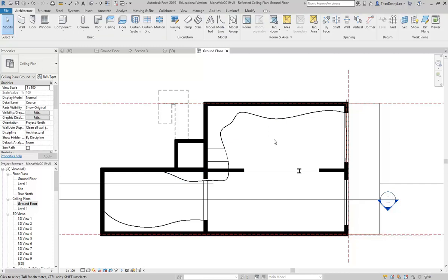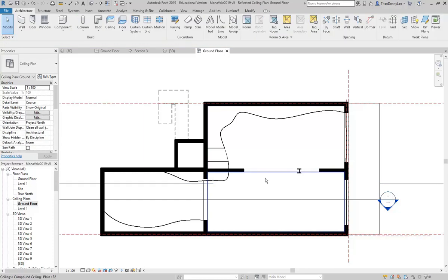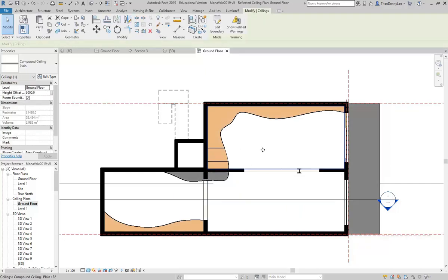That's the way Revit is when you start it up the first time. But then once you turn this setting on, it'll remember the next time you open the program. But of course, if someone else has been using it, you might need to check that. So again, with this option, select elements by face, instead of having to select by clicking on the edge, I can go to the middle and still select those ceilings. Now, they should be coming up a bit more clearly than that. I'm just going to go to shaded so we can see then. So I can select them, but they still aren't coming up all that clearly, even though I can see clearly that it's selected because in properties it's coming up as a ceiling, and when I hover, it tells me the name of the ceiling.